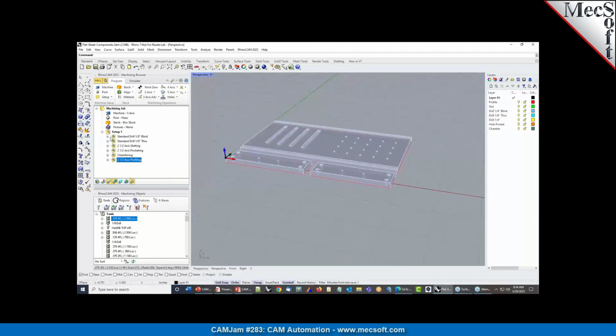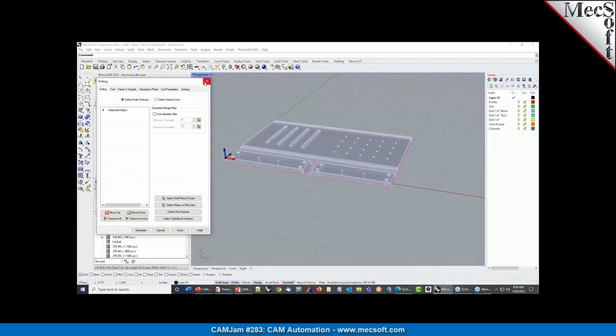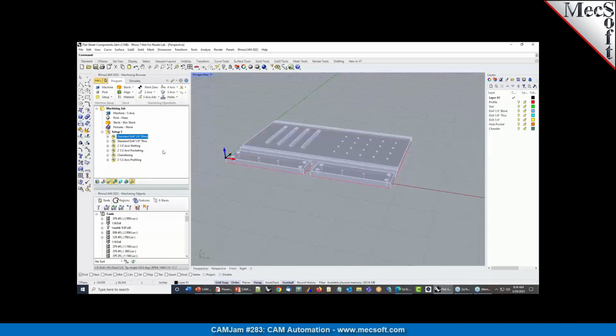At this moment, if you look at each one, there's no geometry selected. So you can't generate it automatically in 2-axis at this point in the automation. And you can automate the selections. I'm going to show you that in just a moment. So even at this level, you can automate the selections. If you look over here on the right, I've got layers set up, okay, with all the geometry for these operations on these layers.